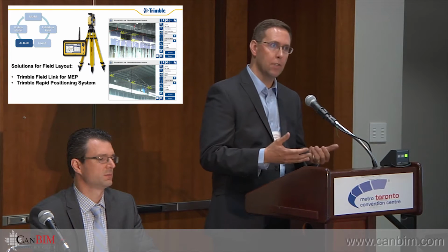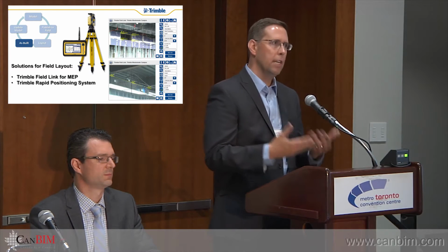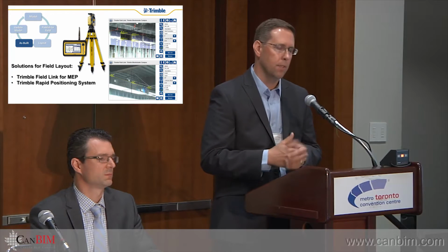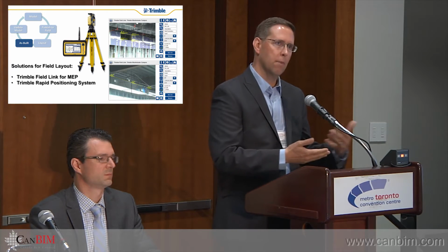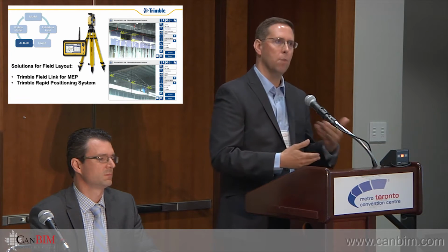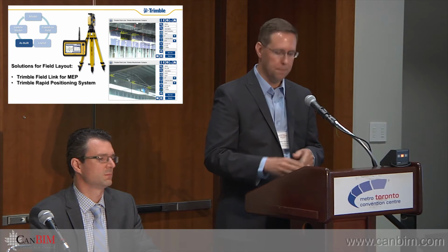And then once you have that information laid out in the field, then you have immediate as-built information. And so those points are representing where things got laid out in the field and actually got installed based off of the actual field conditions. And in addition to that point information, you can also be taking actual images of the field conditions and have those points overlaid on top of those images and be able to share that data back with the office. And then as those points get laid out and staked in the field, you can then push that data back into the office and update your model with the actual as-built location.